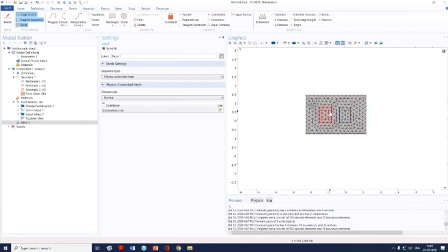In order to select a material between any two objects, if you are just considering the 2D axisymmetric, let's say this is the core, and maybe you are having a conductor, and in between space that you want to have, you need to have a solid domain between those two geometric entities. Unless you have a solid domain created, it will not get meshed, and it will not be considered for any physics assignment.